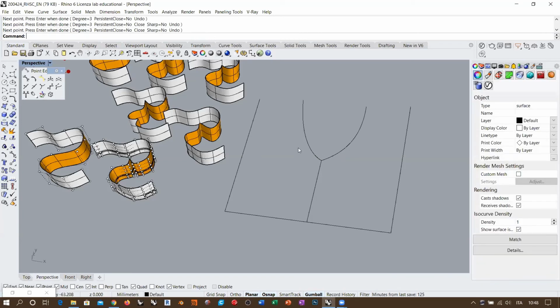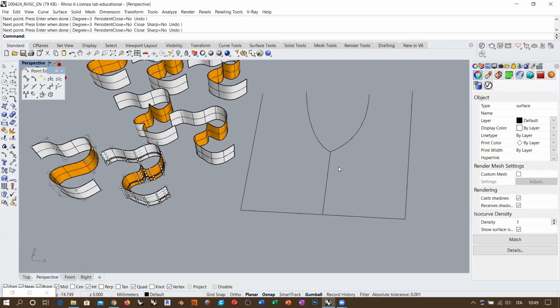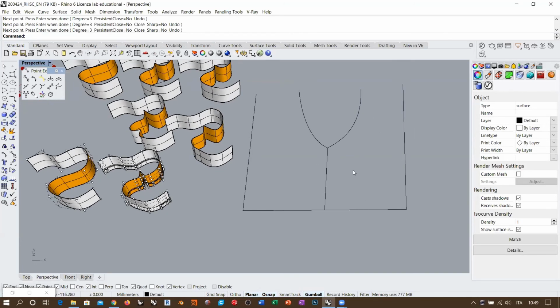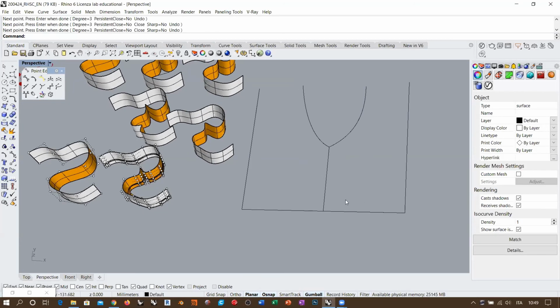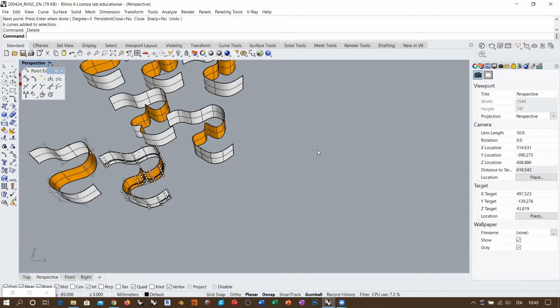So that's why it's called T-splines. You can have branching and different distribution of the topology at different levels along your surfaces. But this is something that is handled by software with a different approach, which normally goes through mesh objects. So this is the difference between NURBS and T-splines.